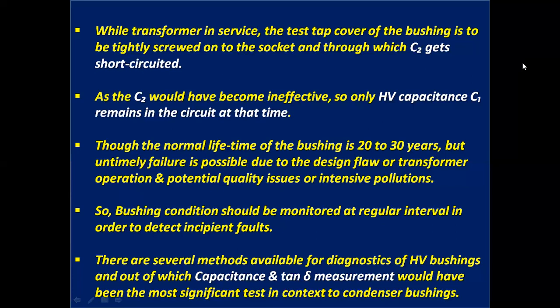So, bushing condition should be monitored at regular intervals in order to detect incipient faults. There are several methods available for diagnostics of HV bushings, out of which capacitance and tan delta measurement is the most significant test in context to condenser bushings.